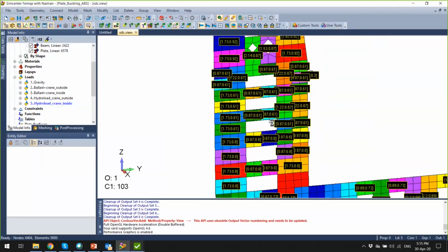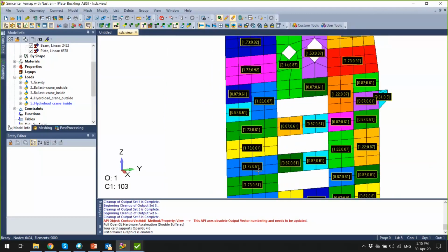And this is very important: you can have a precise mesh, a very detailed mesh with very small elements for your general FEA, for strength calculation or displacements or other finite element analysis you want to have. But if it's surrounded by stiffeners or split by girders or other sections, it's going to be recognized independently of the mesh as one plate, and these dimensions will be used for plate buckling checks.